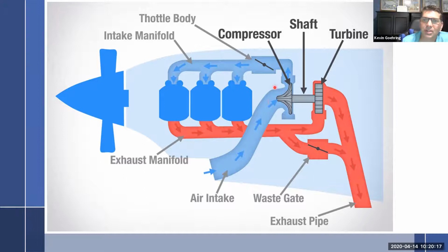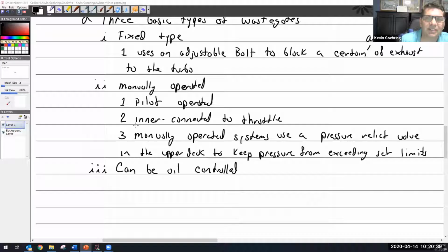And then there's also a thing called bootstrapping, where they tend to pick up, because they compress more air, more air goes through here, because more air went through there, it goes through here, because it did that, it spins this faster, which makes that go faster. So the whole cycle just starts repeating. So they actually get quite complicated in how you want to control them. And so that's why with these aircraft, the whole idea of a manually operated system creates a pretty heavy workload on the pilot. And like I said, we can even make that one step worse and go back and then, yeah, we'll go back. We'll just add complexity to this.